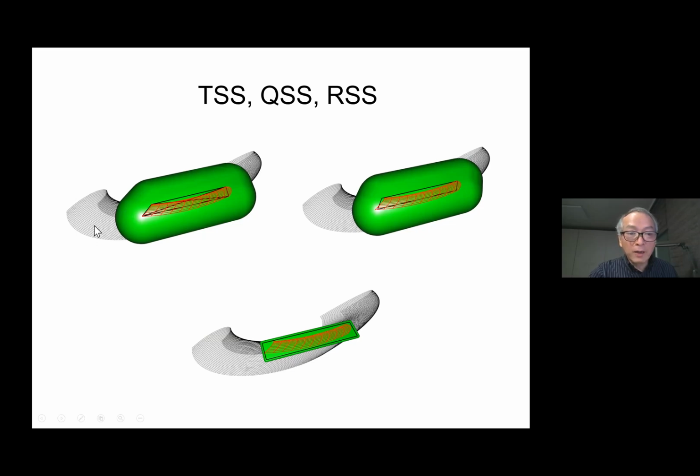You can actually see some more of that effect here. From this big spline surface, we took this small patch, and then using the 4 corners of this patch, we generate the tetrahedra, and we estimate the error between this tetrahedra and the original surface by a mathematical equation. Somehow the estimation was too large, so we have a very thick one. And then these 4 corners are not in the same plane. By moving these points to some mid plane, we have a quadrangle in the same plane. So the thickness was a bit reduced, but these two are just about the same.